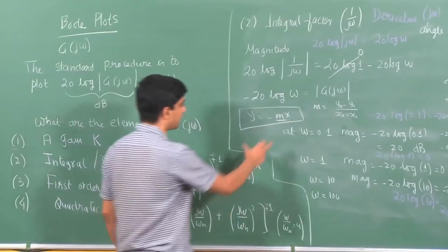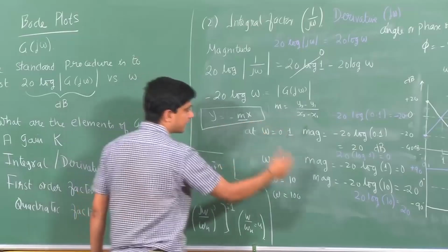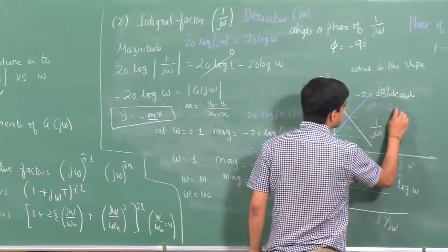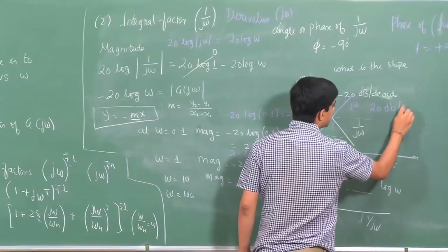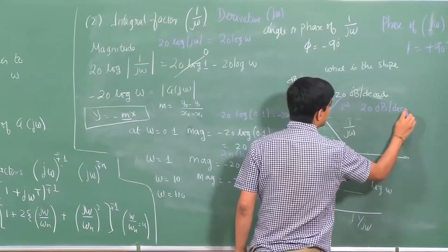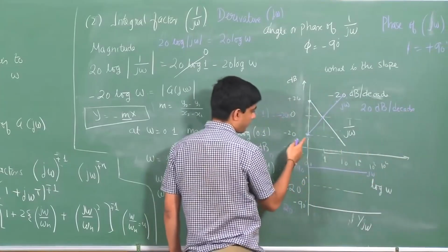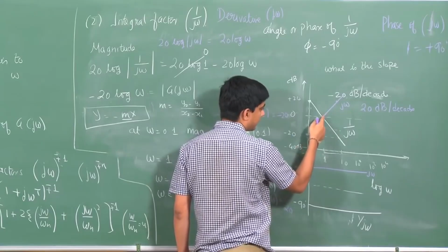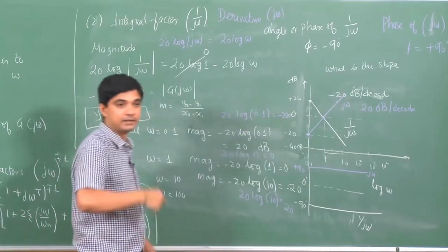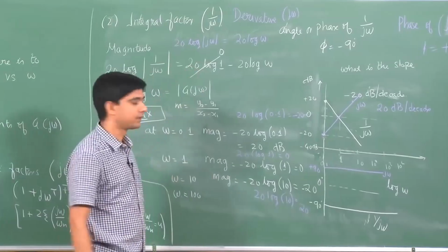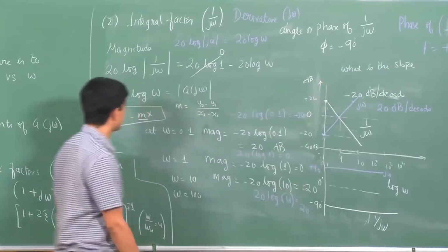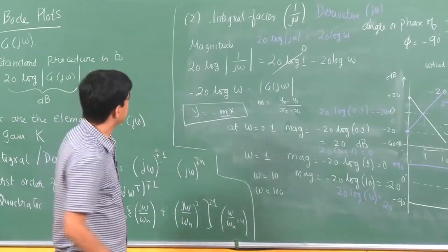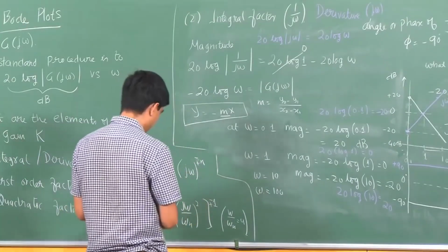Straightforward, right? You just need to remember something like this. The slope of the purple line is positive 20 decibels per decade, because I go from here till here, I increase 20, again I increase 20 and so on. So, each decade my magnitude goes up by 20 decibels in a straight line. Why is it a straight line? Because of this.